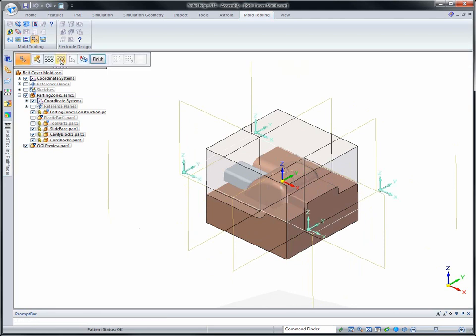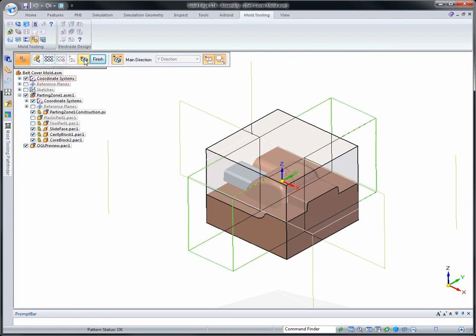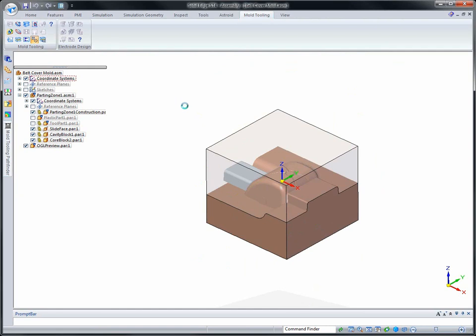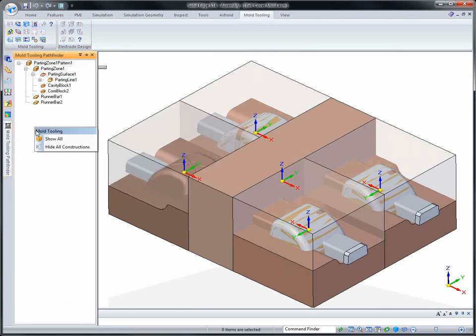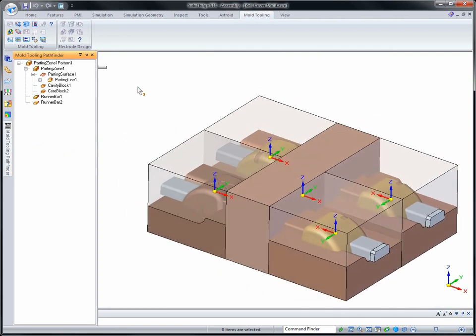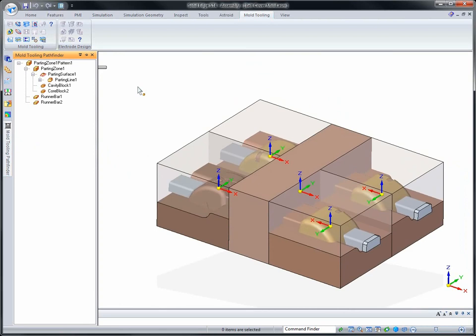And in this case too, I want to include rotating 2 of the cavities, core cavity sets, because of those slides. I have to be able to get the slide in and out. So they'll be 180 degrees off from the original. And then also want to define a runner bar, because I've built in what we call pinch in the mold, so that when the mold comes together, the plates don't hit. The core and cavity actually is the only thing that hits to make the seal. And there you can see we have our core cavity sets, and we'll just hide the construction geometry.